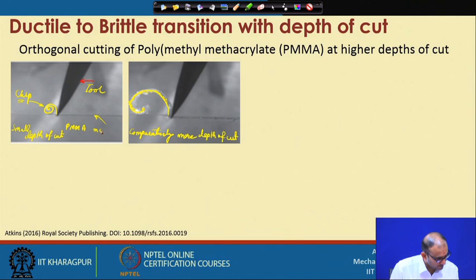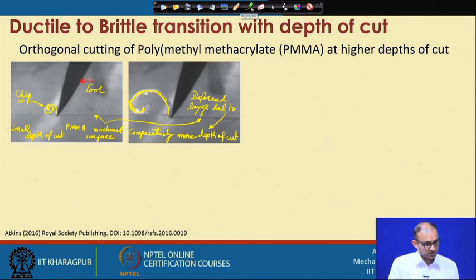If you see the machined surface, and see the same thing here. Now, you can see here it is a very clear surface. That means no material is left uncut, no fracture happens, no cracks, nothing is here. But if you see this particular location, you can find a very clear layer here which is deformed. So, this is the deformed layer, due to more depth of cut. Okay. So, let us continue further.